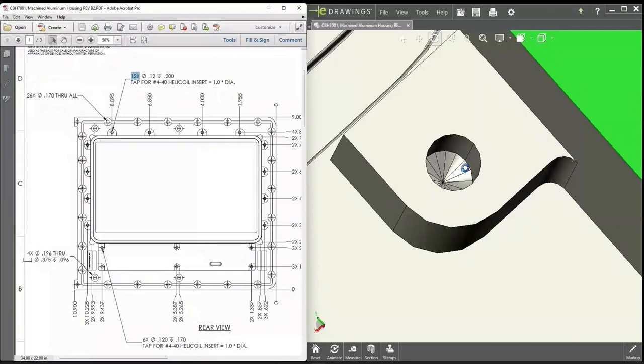As we go back and say, is it possible to change the feature of the hole? Is it possible to go to, again, a flat bottom hole? Is it possible to go to a milled thread instead of a tapped thread? Are there objections to that? Is there a reason for the manufacturing specification that can or can't be changed? So these are all the things that we're going to be looking for as we go through the process.